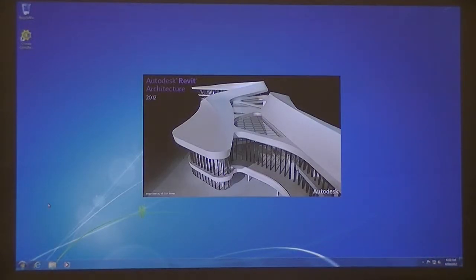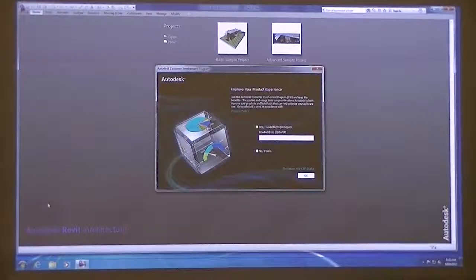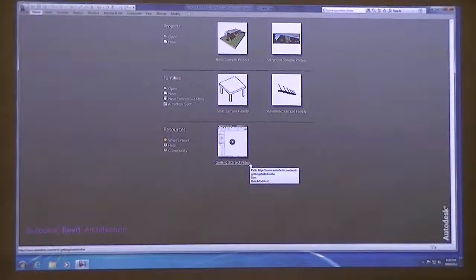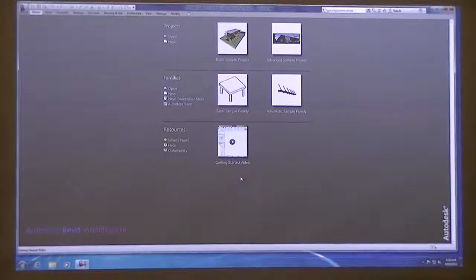You get walls around your elevator shaft. Just draw them? But do you have to do it on every floor? You can just create walls. You could create a wall that has a base at Level 1, and then tell it to have its top at however far you need to go, just like you did with the shaft. So whatever you did with the shaft, you can do the same with the wall. You could do it on every floor, but that.